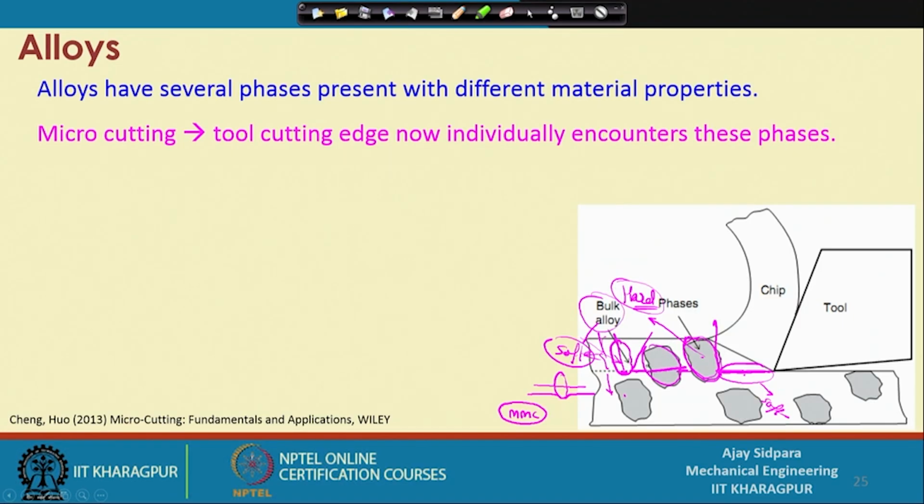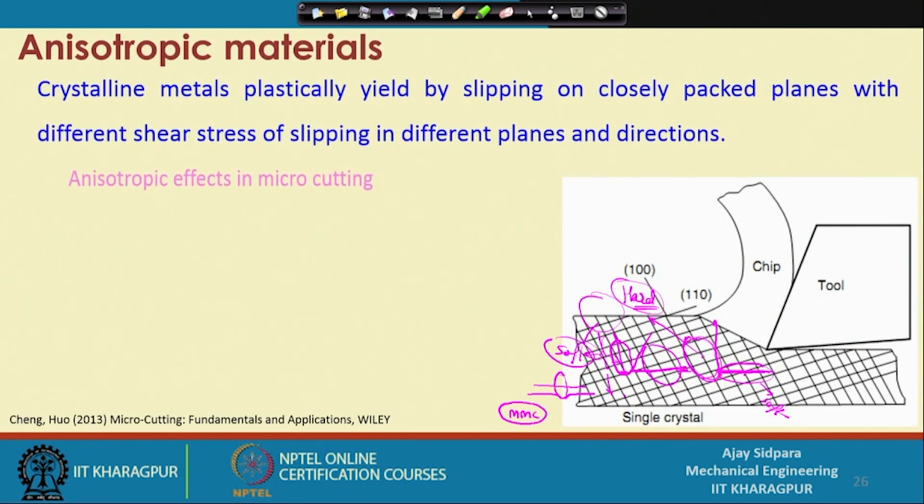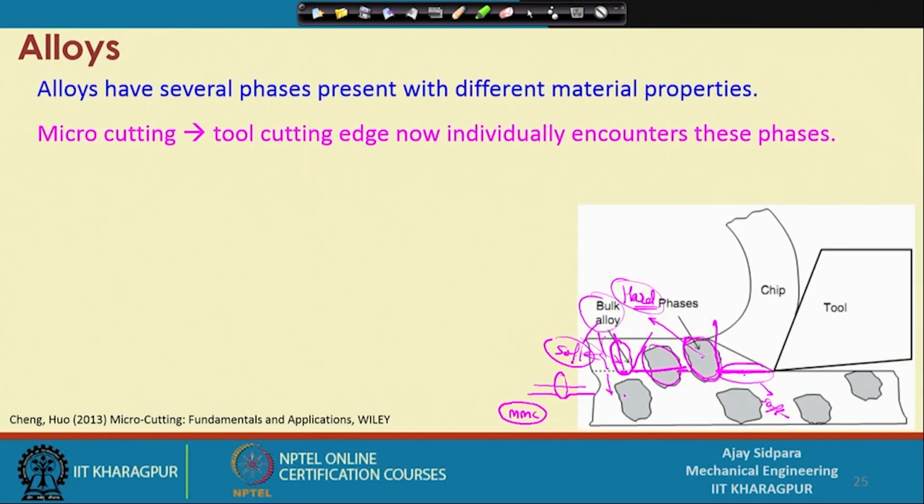Even though it is present on a large scale, in conventional machining it is very easy, because many times this particular large phase will be cut through this particular boundary, and that is the region by which you can cut down this material efficiently in conventional machining, but that is not happening in micro machining, because even without the phase of this alloy, you end up with machining at a different phase, because again this defect will play an important role that we have discussed previously.